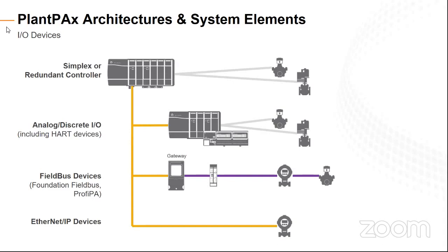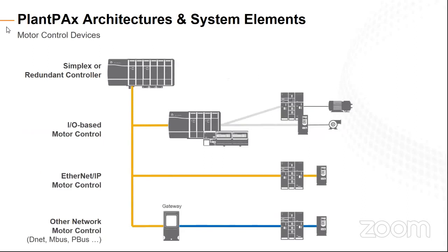You can bring in HART directly into potentially almost every IO platform that we have. If you need to support either Profibus PA or Foundation Fieldbus, we have a gateway product. It converts it over to EtherNet/IP, so all of those feed directly into it. And then if there's any EtherNet/IP devices, whether it's E&H or anybody else, those will come in directly into the system. So those are all fair game as part of the system.